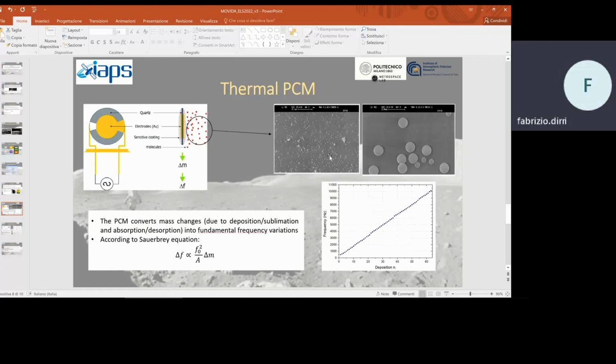These are some figures that were acquired from the SEM analysis. Here you can see some particles on the order of 1 to 2 microns and below. And what is the behavior of these particles? They tend to create aggregates, like fluffy particles, and single particles, as you can see in this figure.